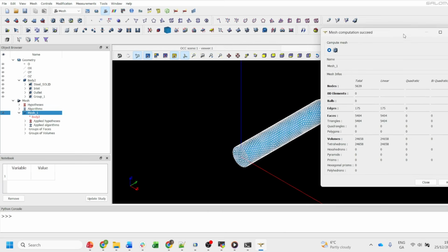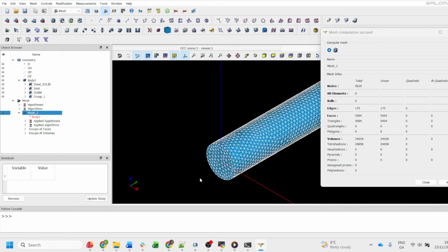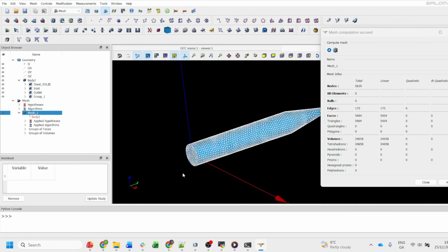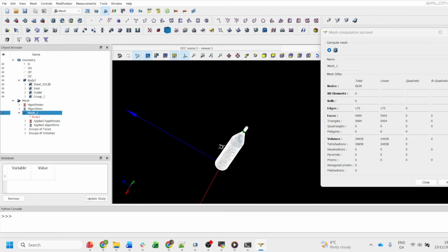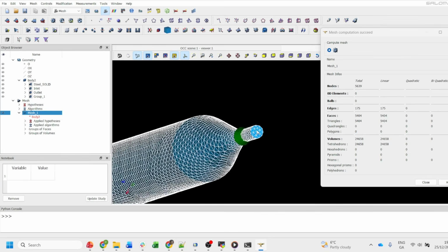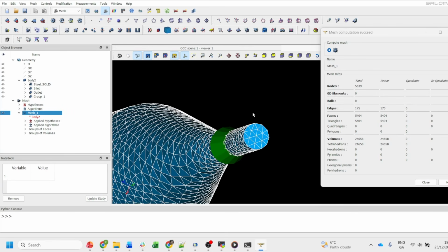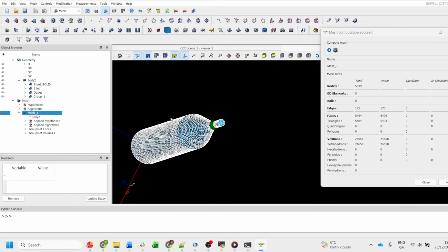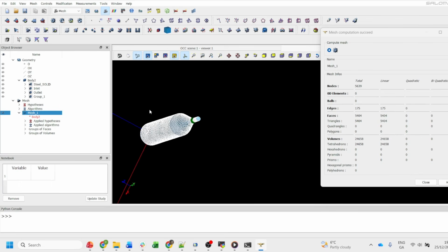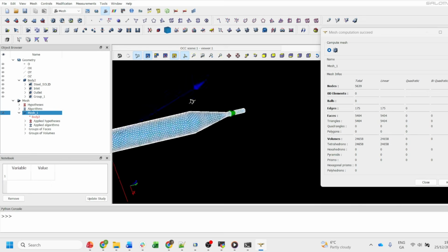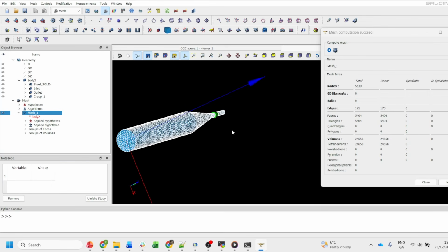So I guess we have further refined our mesh. You can see now I guess the mesh is okay. Just look at the outlet as well. So yeah, it also has more than, I guess, 15 elements. So we will not make it a finer mesh because we want to just run it fast. So now we will use this mesh for our simulation on OpenFOAM.